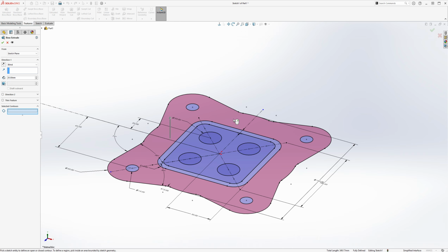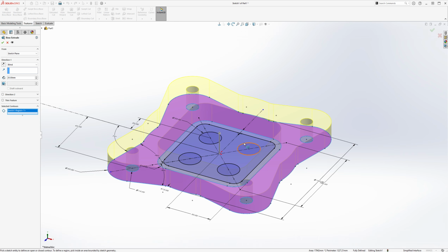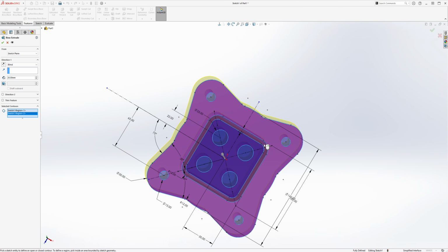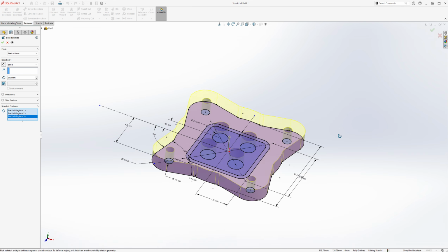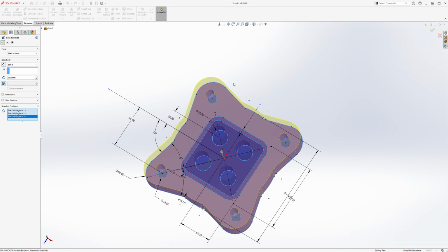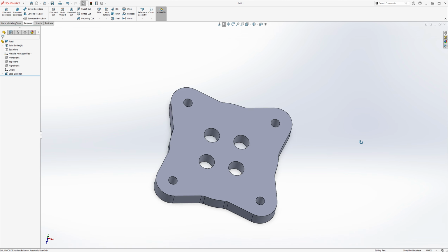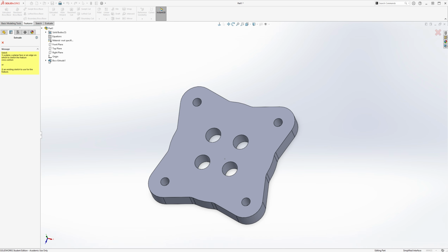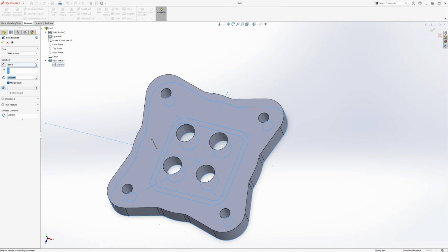Now let's select the base, including this. Actually, let's just select everything. Yes, everything. So select OK. So that's the whole thing. And then we'll do another extrusion. Extrude boss base, clicking the same sketch. Except this time we're going to change the extrusion depth to 25.